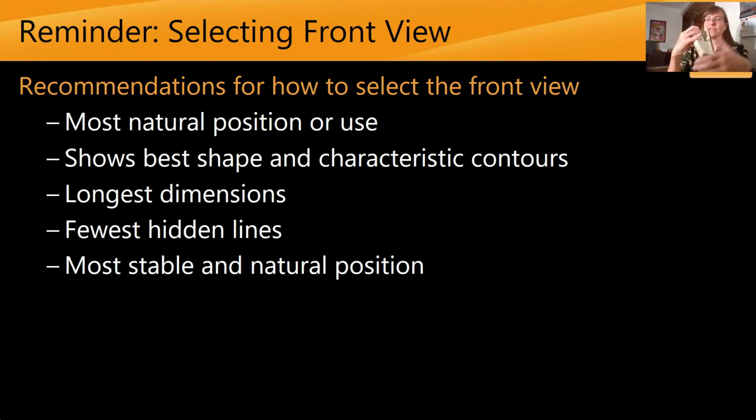So I used my stapler for this example. This would be the logical front face. It's got the longest dimension. This is how you would use it. You're not going to have hidden lines from here, and then it's stable. It's not like you're resting it like this or something. It's stable this way.